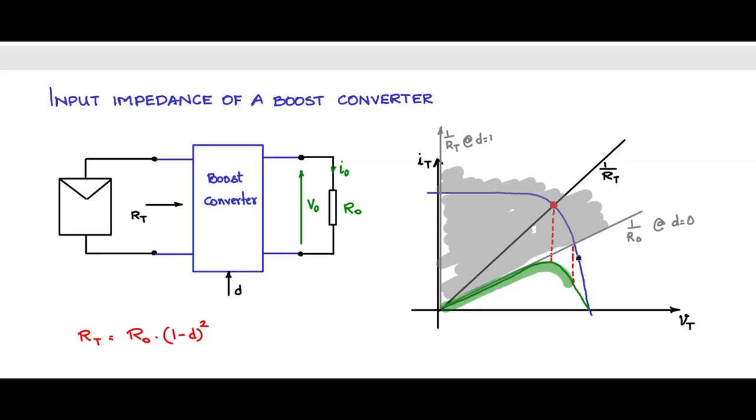So it is very essential that the extreme 1 by R0 load line falls in such a way that a vertical drop down to the power point is on the other side of the peak. It should be noted that the peak is in the reachable portion of the operating points. Then the boost converter has meaning and you can use it. This whole portion is called the range of the boost converter.